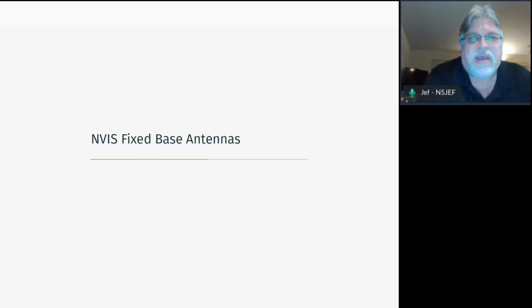Okay, good question. It depends on what you want to do. If you want to use that G5RV for DX and see how far you can talk, maximum distance, then you want it to be about a half wavelength up at whatever band you think is important. So if it's the 20-meter band that you want to focus on with that G5RV, then you want the antenna to be about 10 meters off the ground, and then the reflections will optimize that G5RV for DX.